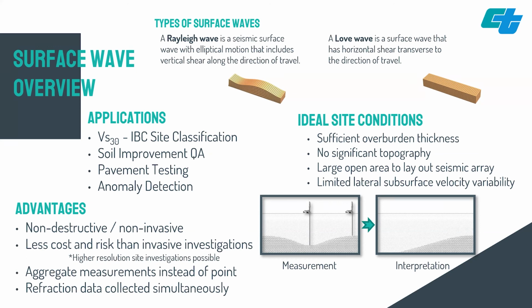As discussed previously, the physical theory and mathematics governing this method are based on a layer cake model in which velocity increases with depth in a planar geometry. And although Love wave propagation can be probed for additional information, the geophones we're currently using are vertically oriented, so our process focuses exclusively on Rayleigh waves.